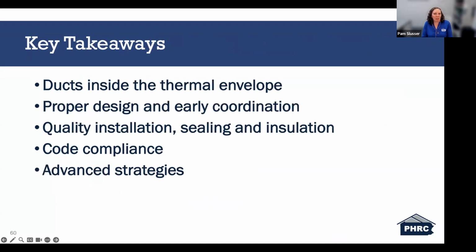So as I wrap up here, some key takeaways: duct location matters. Keeping ducts inside the thermal envelope does improve the efficiency, it improves the comfort, and it improves the overall system performance. It starts with proper design and early coordination, and it's carried through with quality installation, sealing, and insulation. From a code perspective, compliance paths require verified performance through testing, not just meeting minimum requirements.